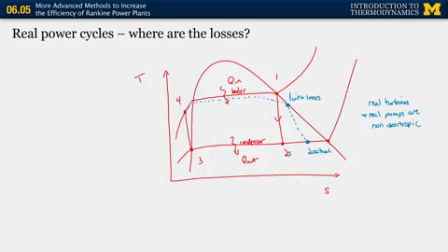And again, just so you have a reference and some foreshadowing for where we're going, turbines are typically 80-90% efficient. In terms of the isentropic efficiencies, they're pretty decent. If you have a lower performer, it might be in the 70 percent range. Okay, but we're going to constrain the system so that it still has to meet the pressure that we were targeting for the condenser.